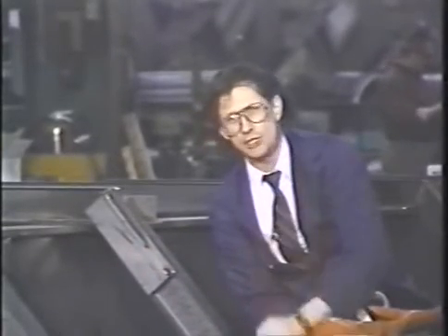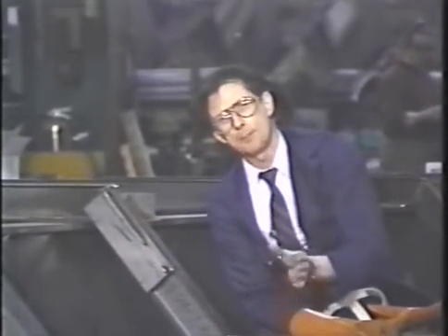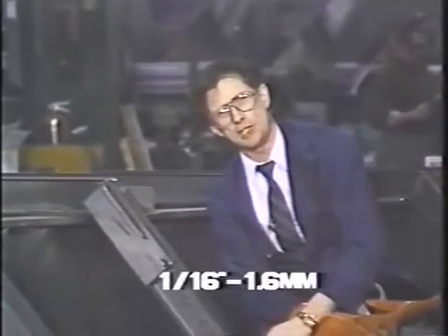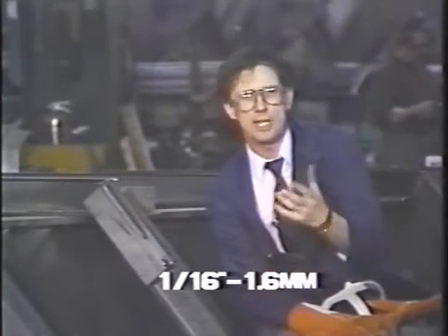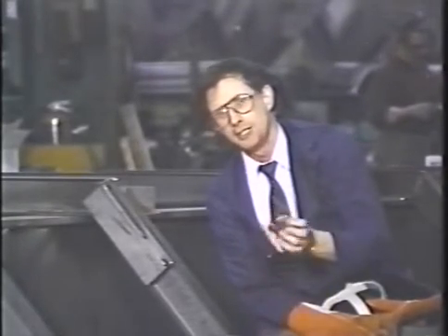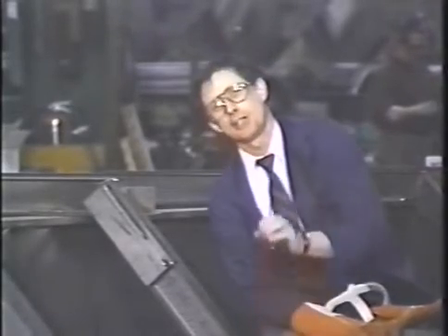But if you constantly weld in a shop and you're welding on sheet metals and you never go above 1/16 of an inch, then it's wise to use maybe 8 to 10% CO2. After all, when you're welding sheet metals, the object is not to burn through. And if we can reduce the heat just a little bit by reducing the reactive part of the gas mix, then it makes it a little easier.